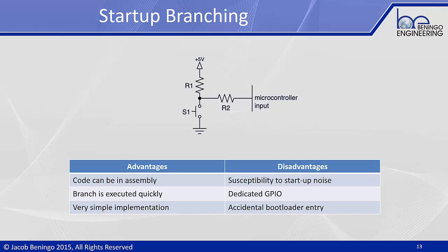Now, very rarely you'll hear me say that that's an advantage, but when you're developing a bootloader and you're trying to make a very fast decision as to which type of code you're loading, whether you're loading the application or the bootloader, you want the decision made very quickly. You don't want to take tens or hundreds of milliseconds to make that decision. So coding that in assembly language at the bare metal could be a big advantage.